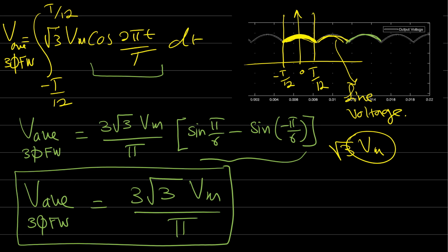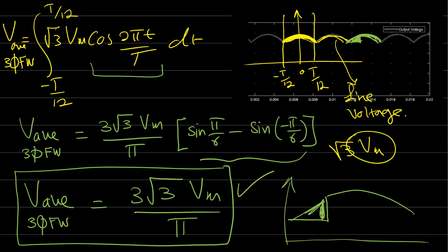If we manage to find the average voltage here and deduct the missing portion from this average voltage, we can find the average voltage for the full wave rectifier with line impedance effect. So now we obtain this value, no problems, without line impedance effect, which is from here to here, all this average. Now let's try to find this portion, and deduct this small portion from the whole average voltage to find this value.